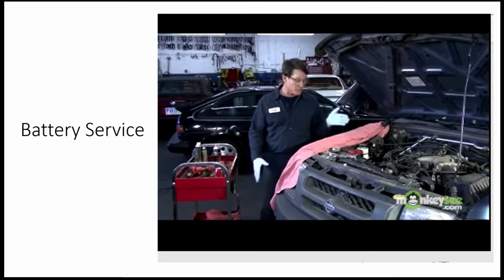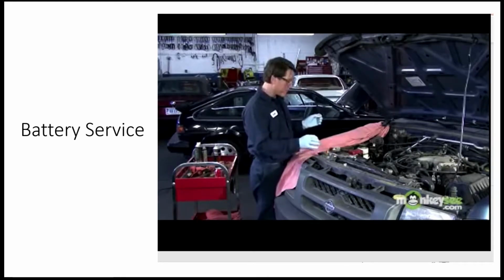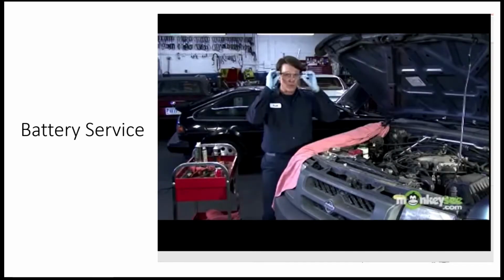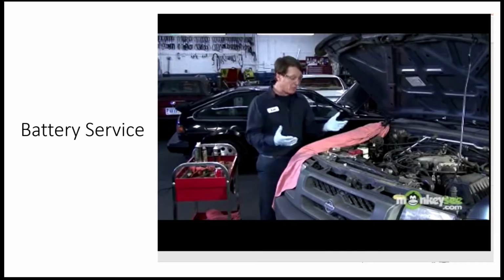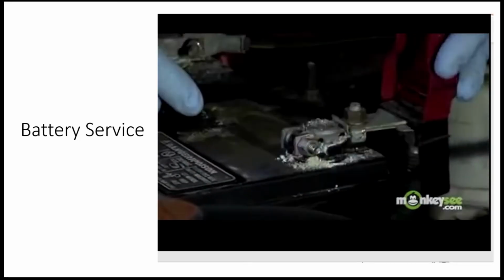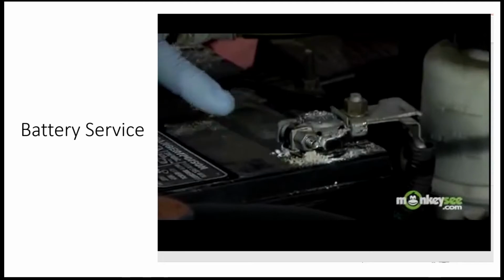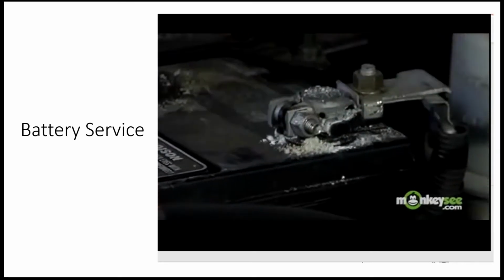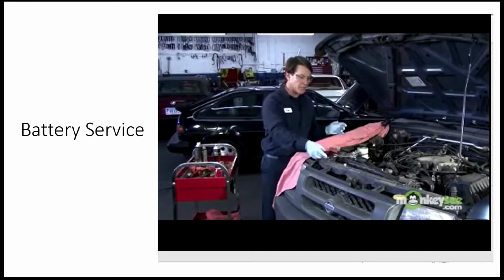First thing you want to do is, of course, look at the battery, making sure of how the terminals are oriented. Remember your eyeglasses and your gloves. We're going to remove the cover and take a look at the positive cable. We can see that there's a lot of corrosion around the positive, where generally you get more corrosion than on a negative cable. So let's proceed with cleaning it.